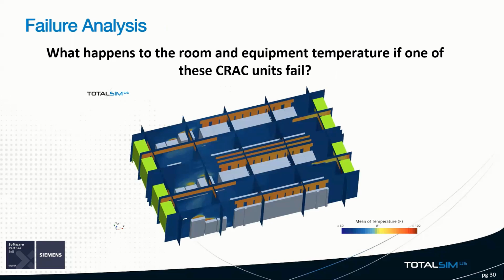Reliability has often been a critical concern when designing and constructing a data center. What happens to the room and equipment if one or a combination of these HVAC units fail? We can use CFD to simulate and predict temperature and airflow when these HVAC units fail. We can simulate the failure of each unit or a combination of different units.